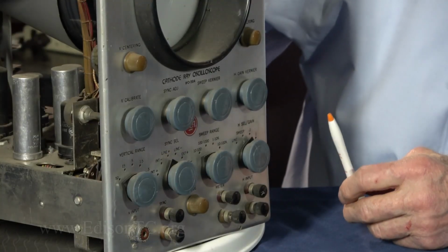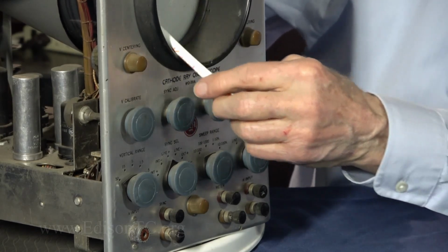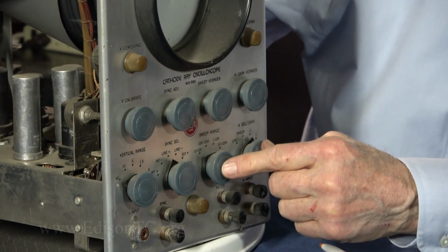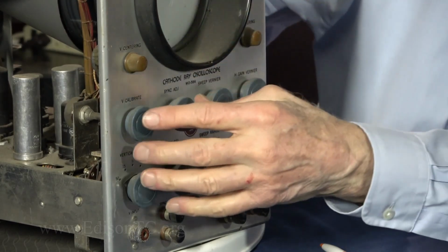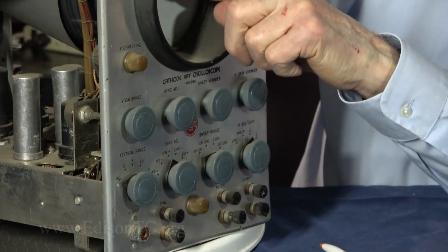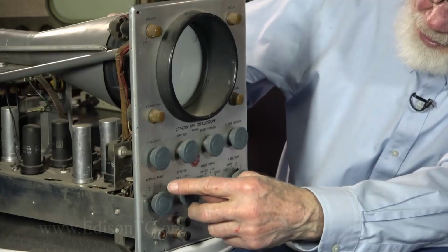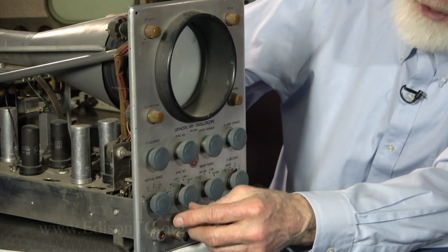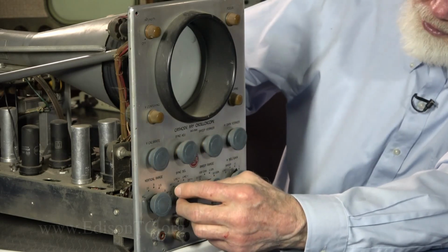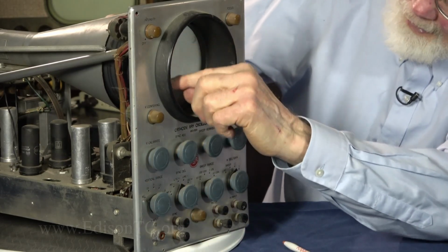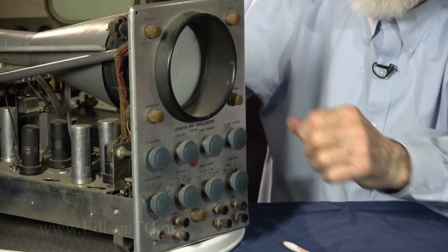To make a measurement, you needed a calibrated time base so that you would know how fast the trace was going across the screen. And these controls on this side controlled the time base. You would also need to be able to calibrate and be able to measure voltages. Some voltages would be very high, some might be very low. So these knobs over here gave us the ability to measure very small voltages, and we'd amplify those. And for very high voltages, we'd actually have to attenuate those voltages. And that would then give you an amount of deflection per volt. And you could then measure what's going on.